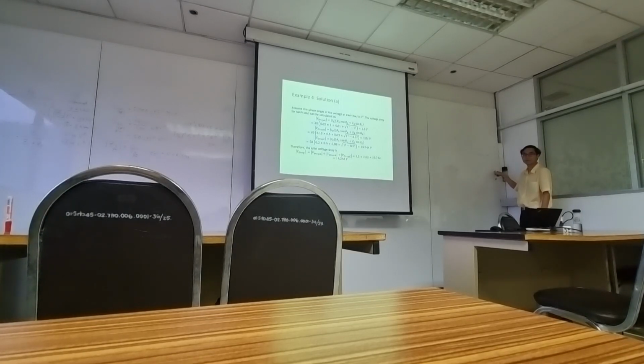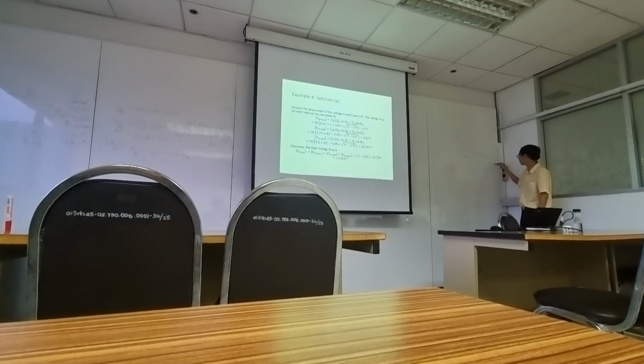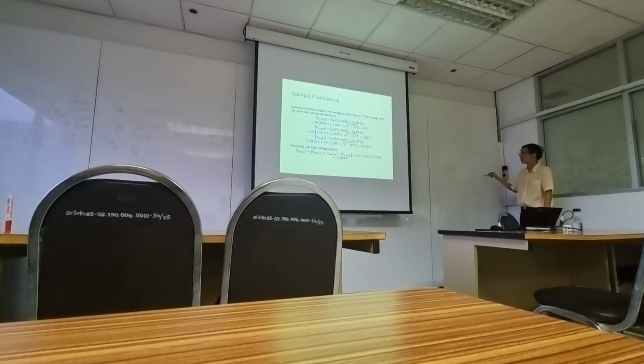How about this voltage? Same as Va. There is current flow from the source to Va, but from here to here there is no current because this is open circuit, so the voltage along this line is the same.